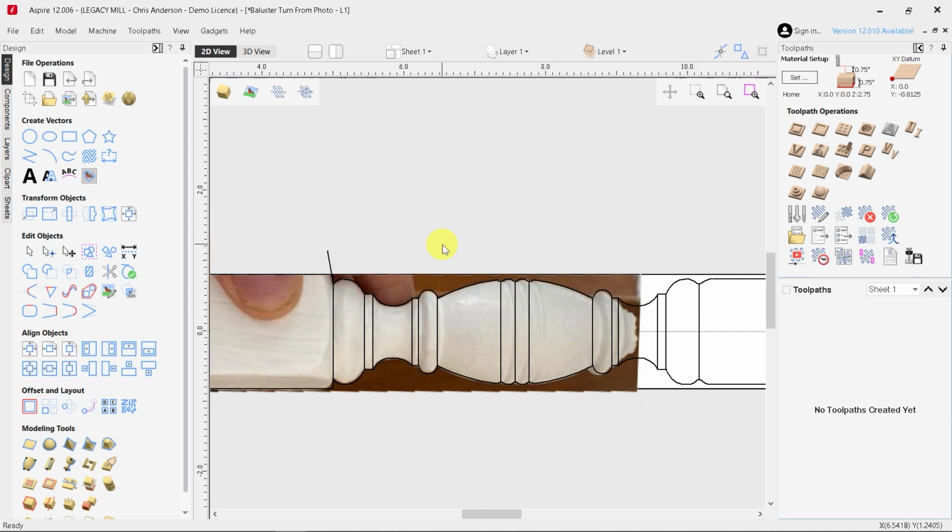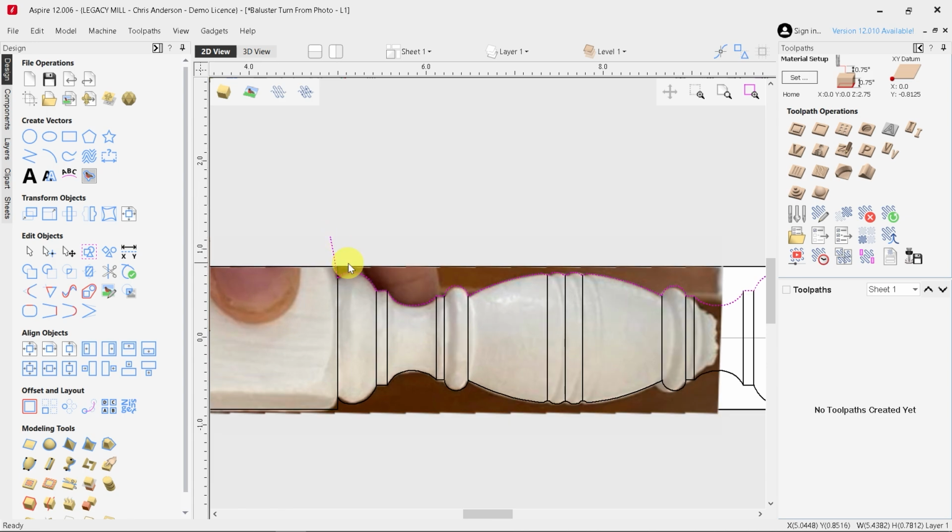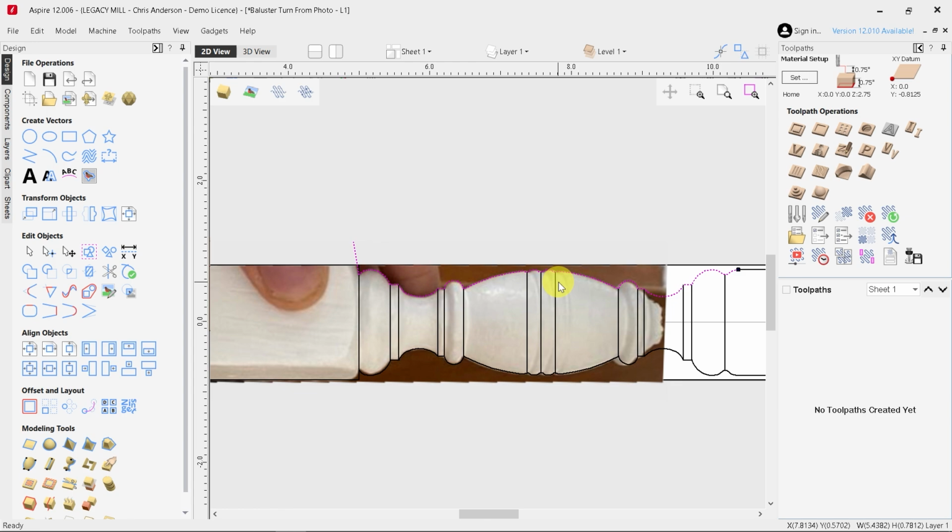However, this new method with Conversational CAM Pro allows us to take a G-code file that we generate here in Maverick, and this will just simply be a 3-axis flat stock toolpath. So the cutter, for example, will cut on this side of the line, just following that shape, using X, Y, and Z, no rotary for the Maverick software.